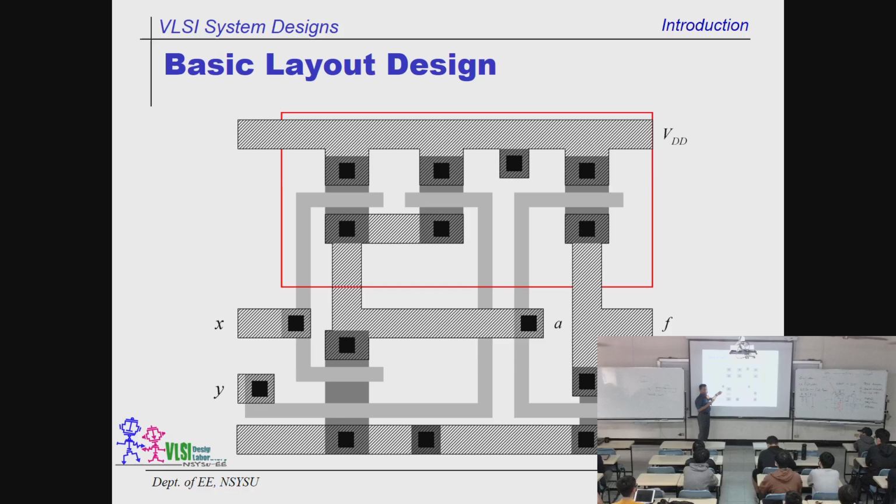This stands for polysilicon. It is also a conductive material, but it's not a metal. Right now we are going to couple the metal and the polysilicon. It's just like going from the third floor to the second floor. You cannot directly jump; you have to have a stair or an elevator to go up and down. So the signal goes through the hole, because it is a stair, down to the next level, which is the polysilicon over here.